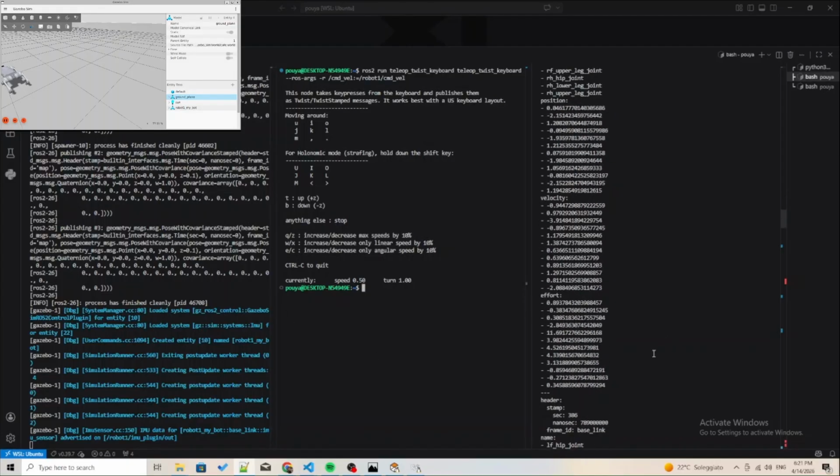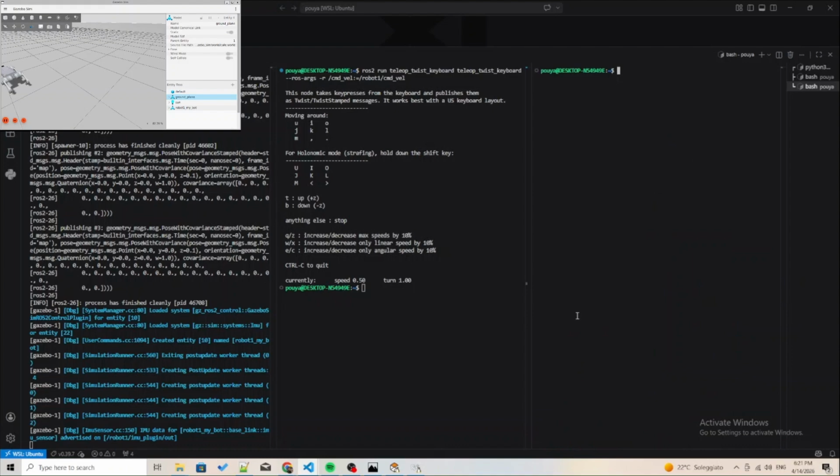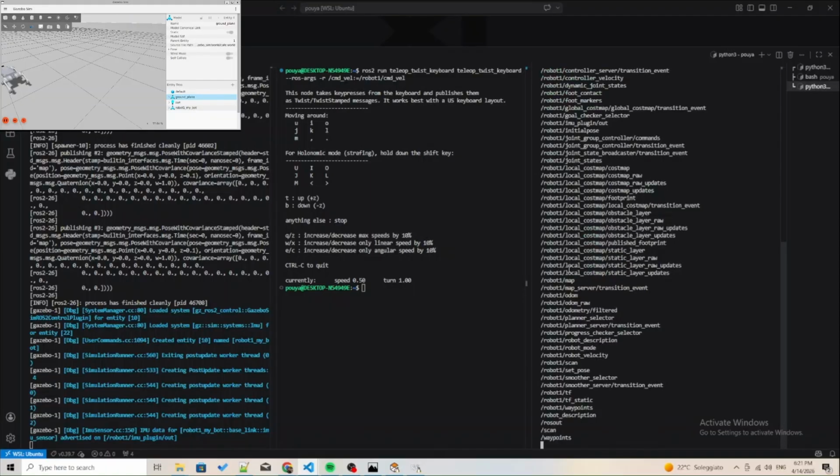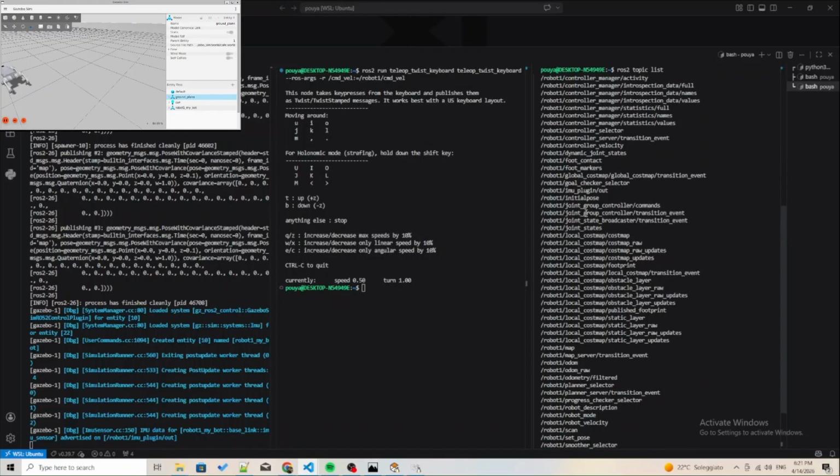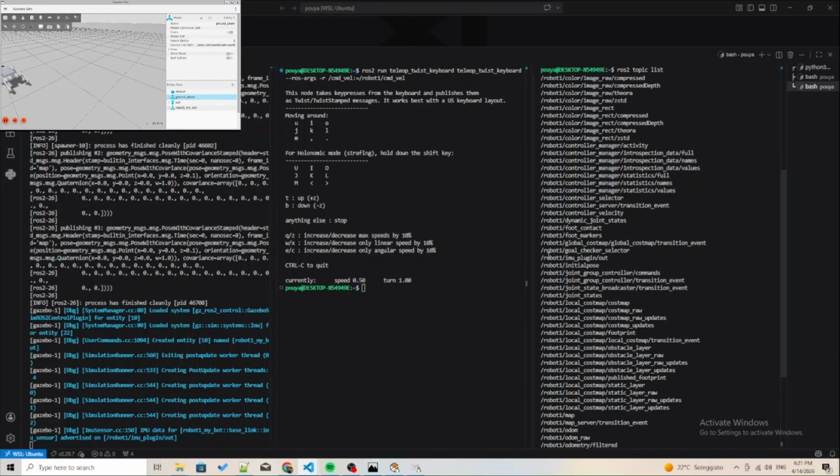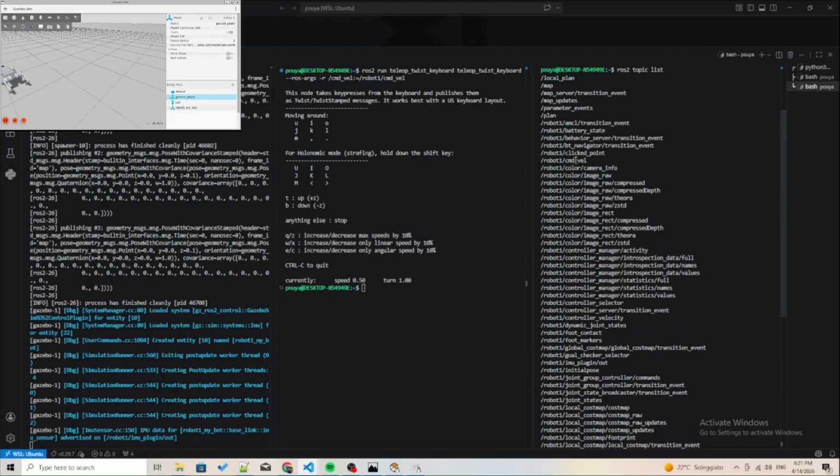What I have chosen to do is, let me first show you again a list of topics. ROS2 topic list. I'm going to use geometry messages or cmd_vel. Robot 1 cmd_vel. Okay, here we will use this topic, and instead of listening to it, we will publish a new one.